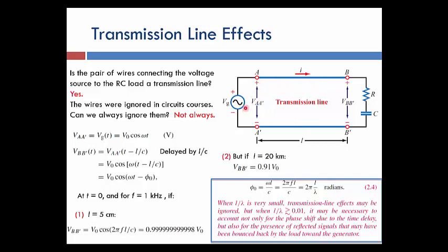That's because with a high frequency electrical signal, these two parallel wires do not look like just two parallel wires. They work as a resistance and reactance elements like capacitors and inductors. According to the behavior of the capacitor and the inductor, these two wires will store the energy inside them and then release this energy. So it could travel, according to their values, in the opposite direction and cause the reflection phenomena.